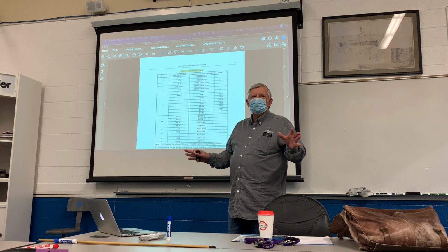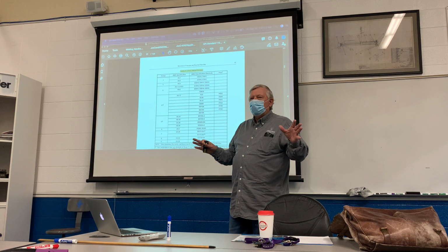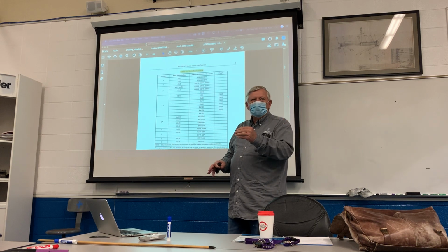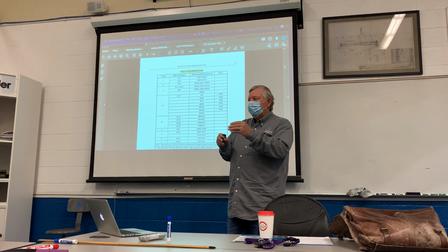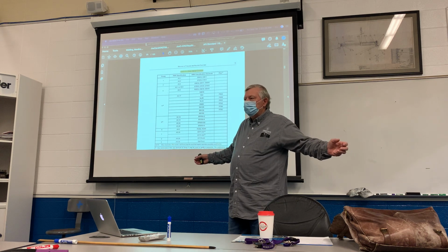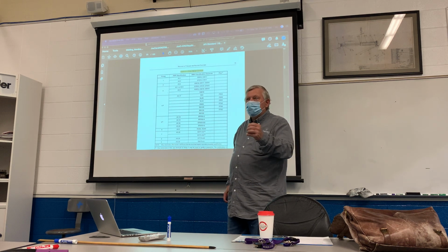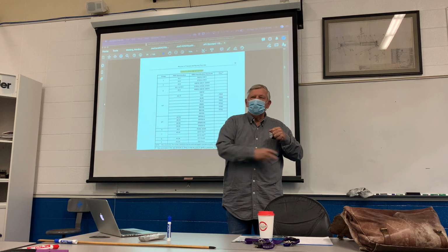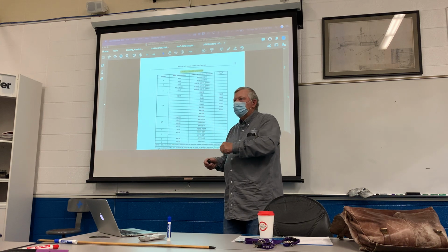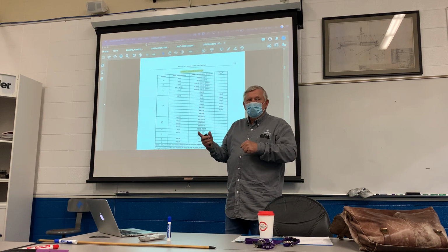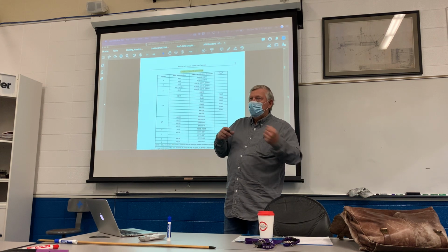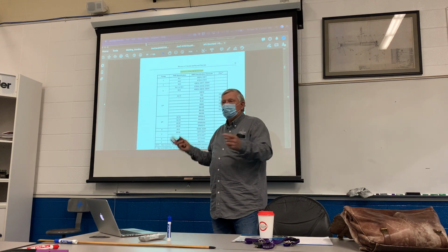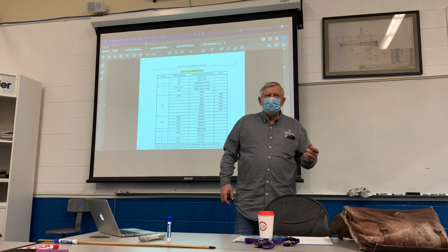What is the reason you preheat? You preheat so that when that arc welding is being done, the heat from that weld isn't sucked out of the weld. You got to have a minimum of 200 degrees. He's got to be standing there ready to strike the arc. When that temperature is pulled off, then he can start welding. All right. Then you have to maintain an interpass of so much and an interpass maximum of so much. You have to stay within that range. Why? Because of metallurgical reasons.